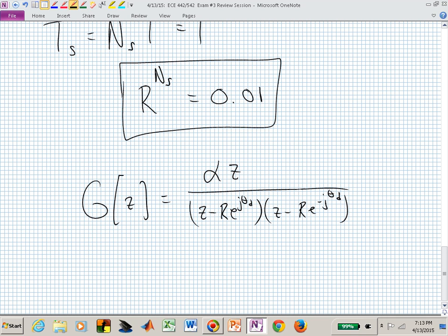Yes, so now if you're doing the direct design, you're going to have to simply realize that these formulas that we're using to specify the denominator are really only approximations. They're rules of thumb based on an ideal transfer function, and that ideal transfer function goes out the window a little bit if you have unstable zeros, because you have to preserve those.